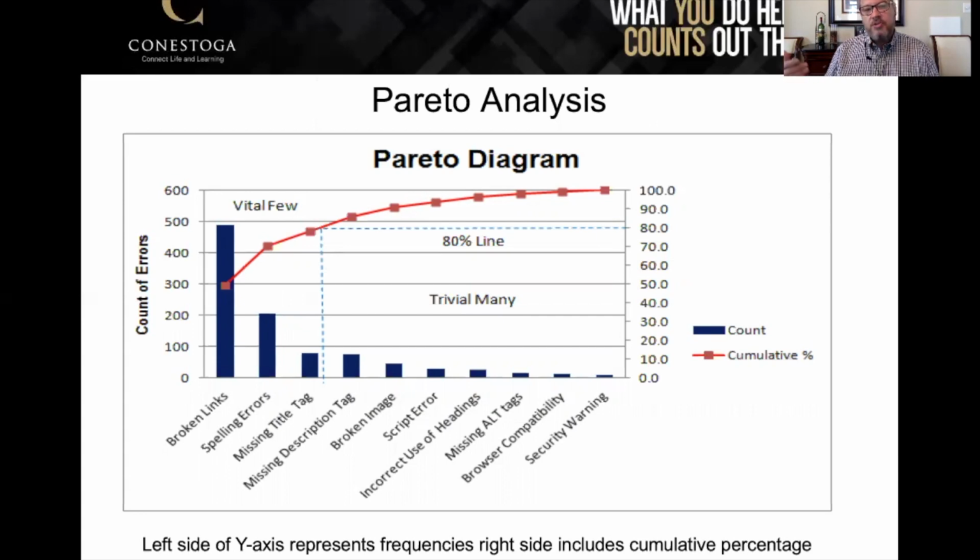And then when you chart your Pareto, you do it based on the frequency of occurrence, and then you rank order it so that on the left-hand side are the most frequent occurrence, and then tailing down towards the right. And what you want to focus on is those handful of ones on the left-hand side that cause the vast majority, or in fact 80% of the errors.